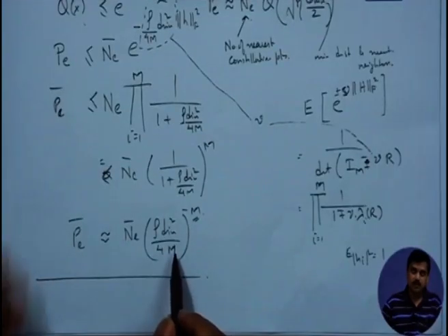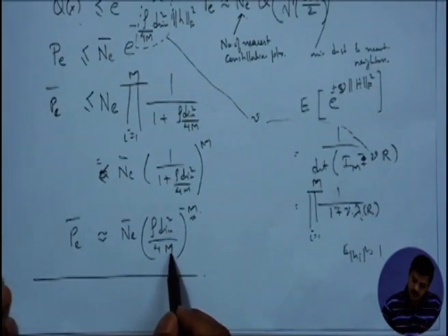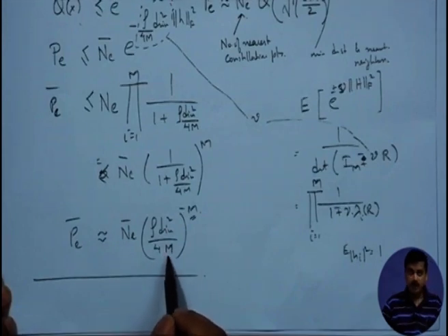We were in the previous lecture looking at the different ways of calculating error probability, and we have also taken the general criteria of diversity, where we said there are m parallel transmissions. These parallel transmissions could be in time domain, or in frequency domain, or in space domain, and we had arrived at the general expression of error probability, where the m in the denominator came because there were m parallel branches, and the transmit power was divided among the m parallel branches.